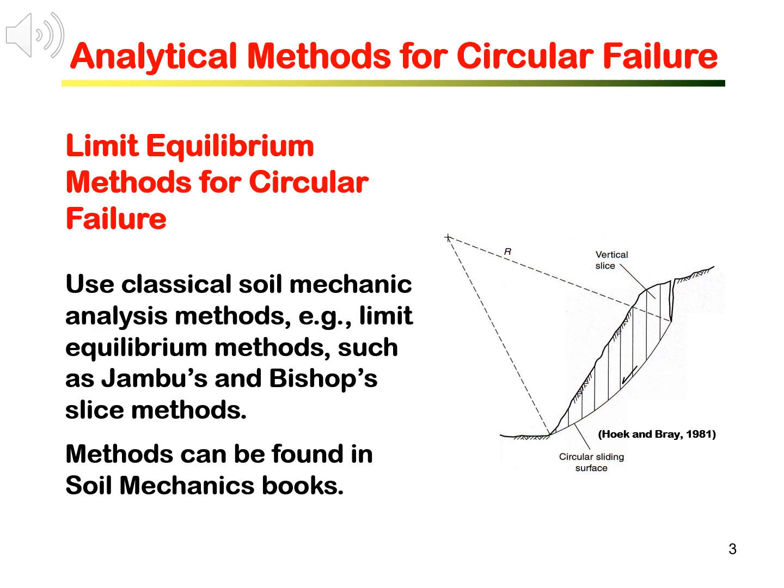This is what soil mechanics adopted for slope stability analysis, using the limit equilibrium methods. The slope is usually simplified into two-dimensional. To formulate the equation, the technique of method of slices is commonly used.